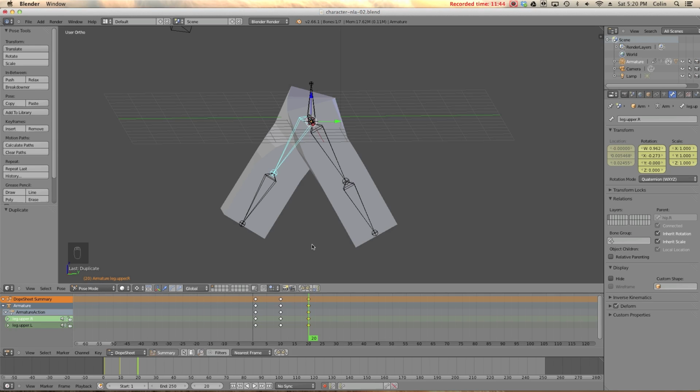But here's the thing about Blender and animation. When you make an animation in Blender, you're not just making keyframes along some random timeline. It's actually stored in what's called an action. The way that you can access these different actions, in other words, little blocks of animation data, and put them onto a character or an object, is using the Action Editor window.